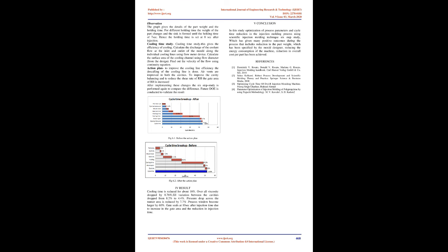As a result, cooling time is reduced by about 16%. Overall viscosity dropped by 8.76%. Fill variation between the cavities dropped from 8.2% to 4.4%. Pressure drop across the runner area is reduced by 7.7%. Process window became larger by 60%. Gate seals at 10 sec after injection time due to the increase in the gate area and the reduction in injection